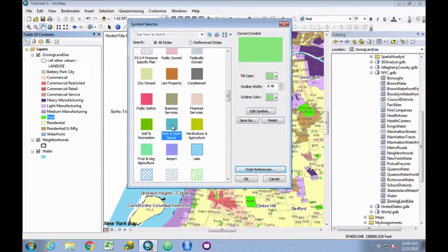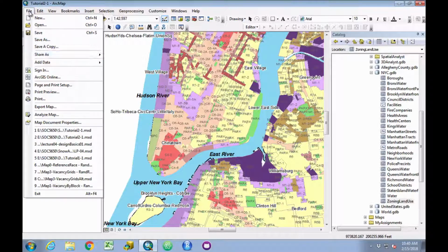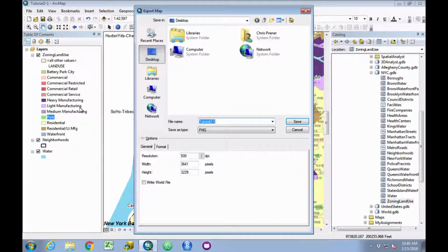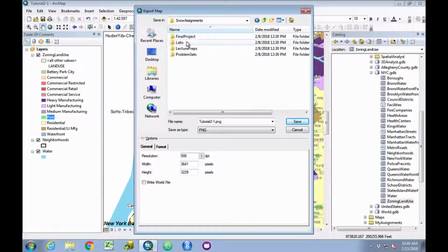After this lecture prep is done, you'll want to make sure you go back and uncheck the Civic styles from the list to hide them again. Finally, we'll save the map document and then go to File, Export Map. We'll navigate to our external device in the dialog window and save our map output to the results folder in our project hierarchy.